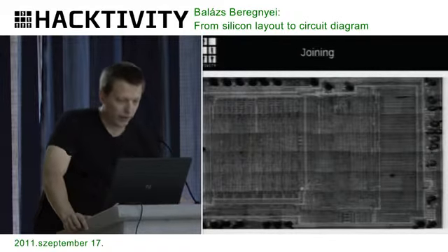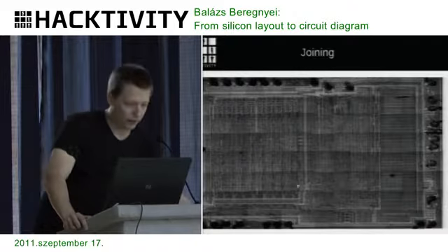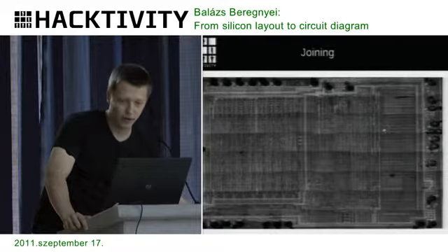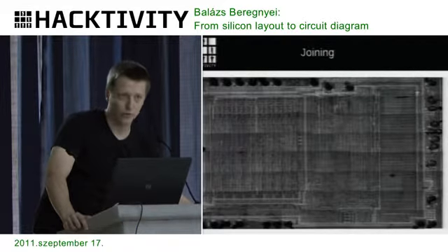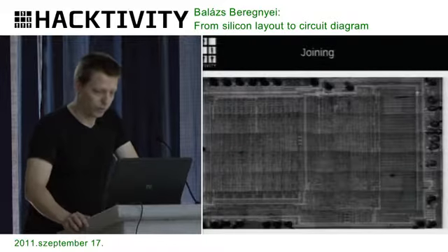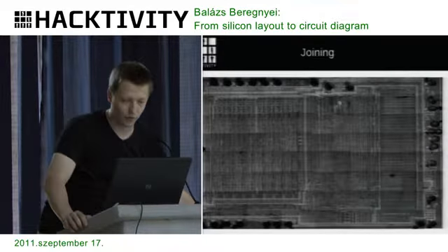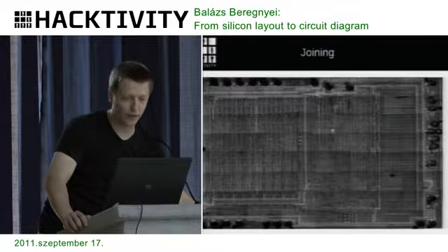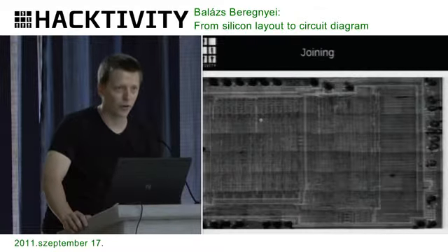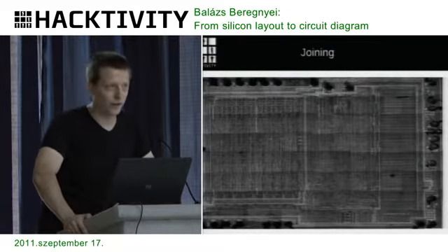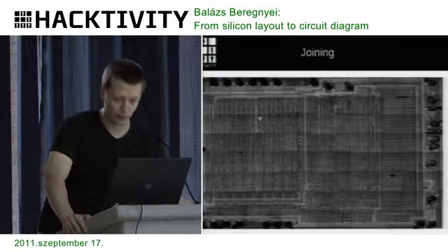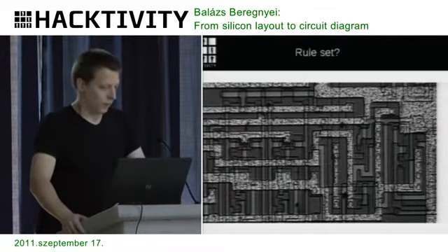This is the register block. Here you can see immediately that it's an 8-bit processor. Roughly you have 8 columns, and the registers are aligned horizontally. On the right hand side you have a well-ordered structure. This is basically a table and a ROM helping the commands or the instructions. And here we control the data flow in the register block.